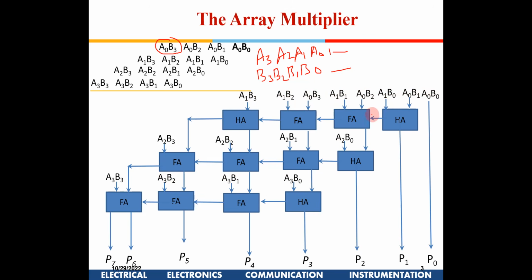All these 8 bits, 4 bits of multiplicand and 4 bits of multiplier, are available at once, so you can use a lot of AND gates and get all these AND results in one go. All these are available after one gate delay.